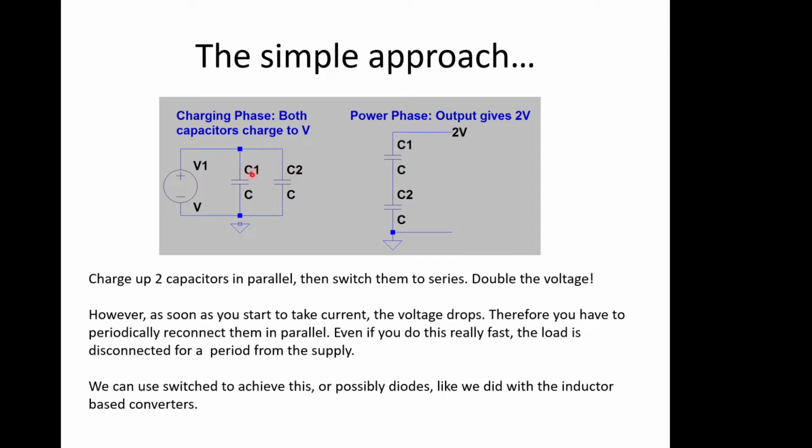But I always think that it's a lot more intuitive with voltage driven systems. So if we break this connection here and take this capacitor and stick it on here, then we've got a potential difference of 2 volts across the two. So we double the voltage.